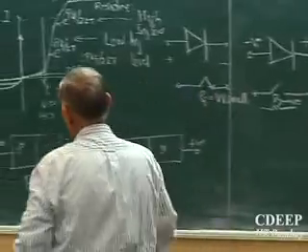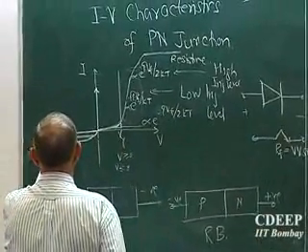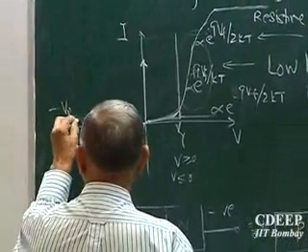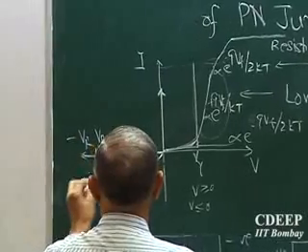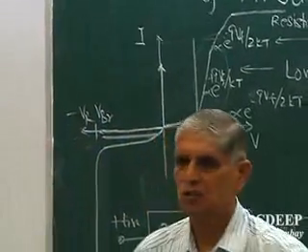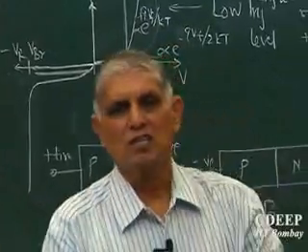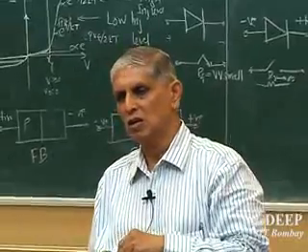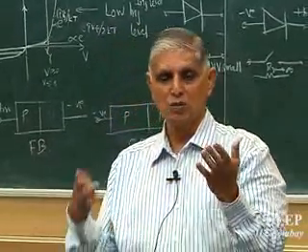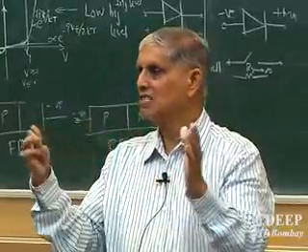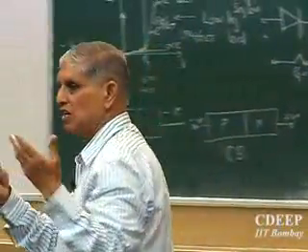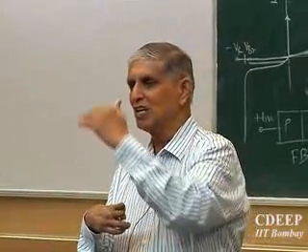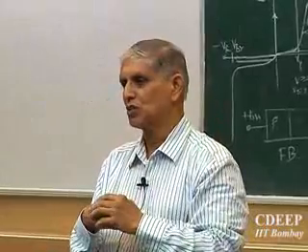We also see if I keep increasing the voltage in this reverse bias, at a certain value, call it breakdown, the current starts. That means the device short circuits as you cross that value called breakdown. In reverse bias, the depletion layer is enhancing, more and more electric field is created and therefore very few carriers really can go. Is that clear? And therefore practically zero current or very small current flows.